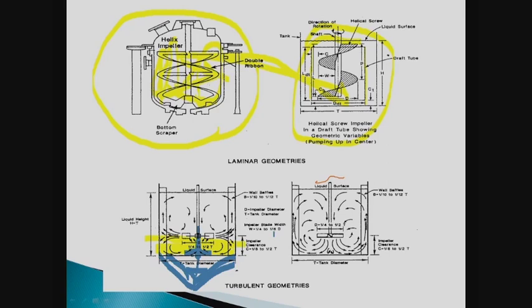I don't particularly care for radial flow impellers because what happens is they compartmentalize right down through the middle. This up here may be quite well mixed. This down here may be quite well mixed. But cross mixing between those two volumes may be somewhat limited.